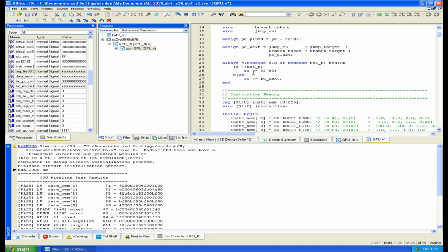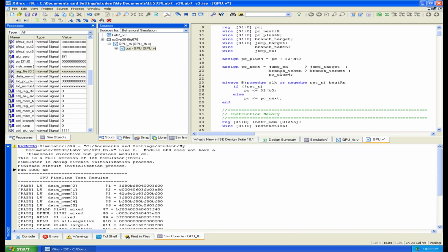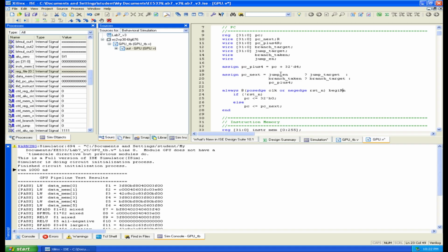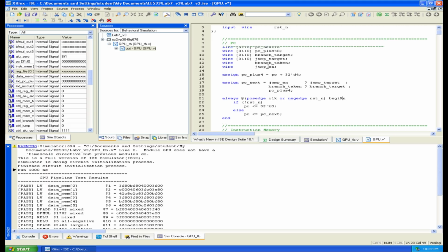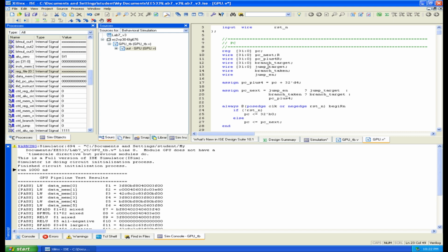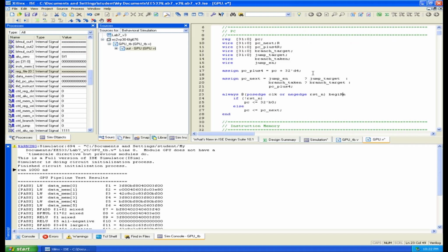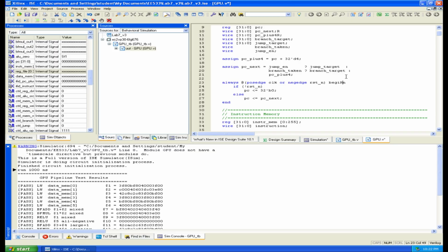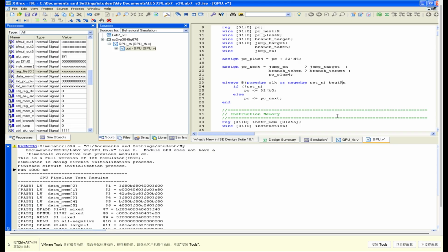other modules. And so basically our idea is just use a 5-stage pipeline architecture and add a tensor unit into the EX stage, and we use almost the same instruction type with about the same type of CPU in Lab 5 or in Lab 6.